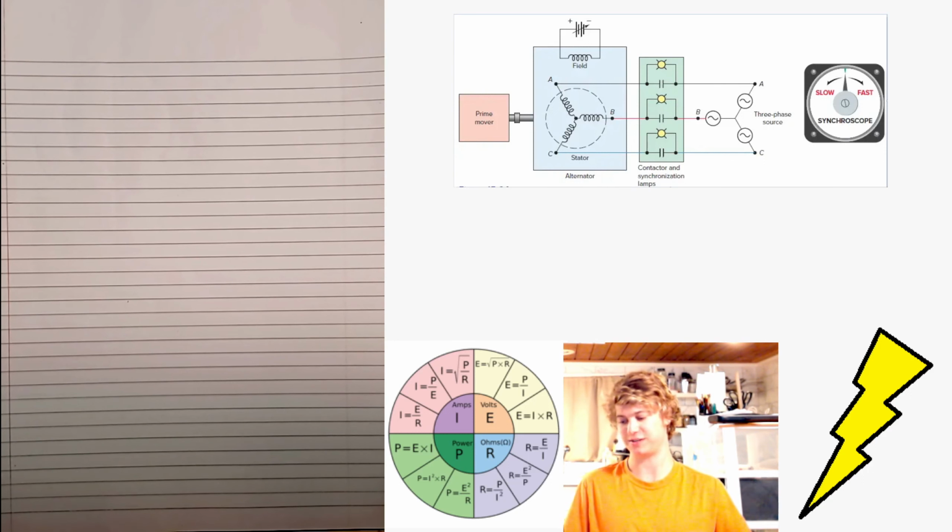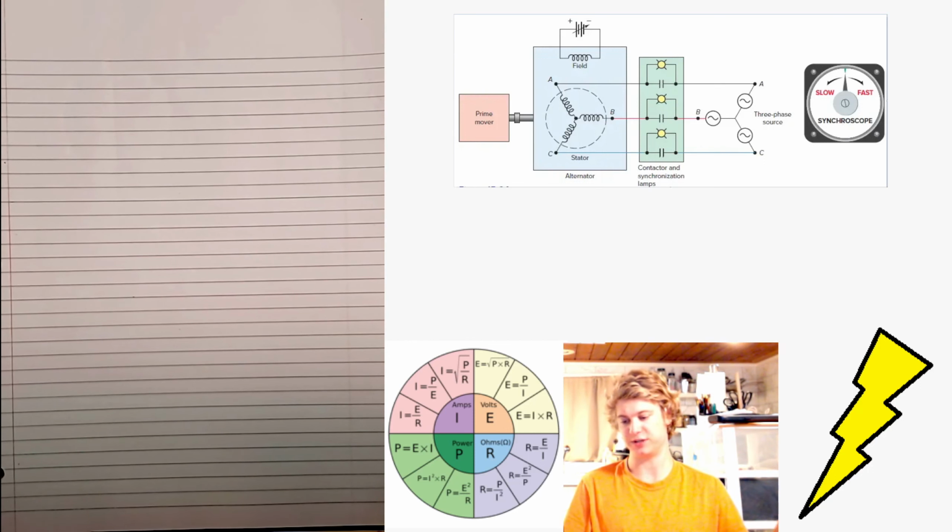So in the past, synchronizing was performed manually using the three-lamp method. Today, the synchronization is carried out much more accurately at the exact instant of synchronism using a synchroscope. The synchroscope meter display will indicate whether there is a speed/frequency mismatch and/or a voltage mismatch between the two sources that are being paralleled. Since the synchroscope meter movement can travel in a 360-degree direction, when changes are made that affect the frequency and voltage output, the effects of those changes can be observed as they are made.